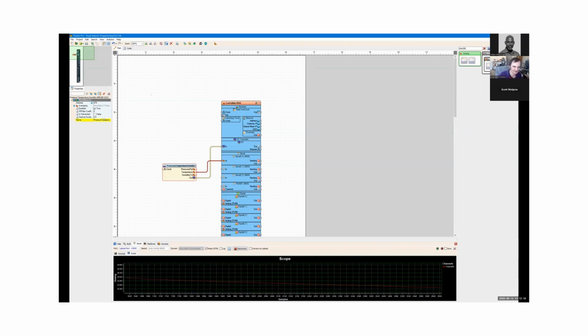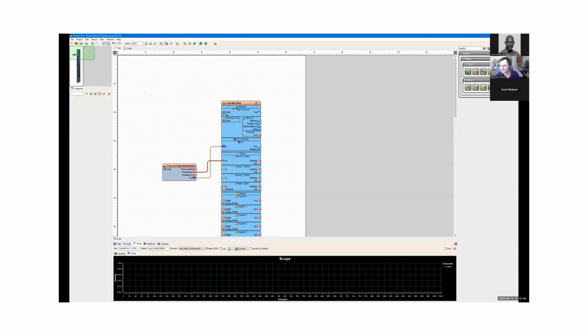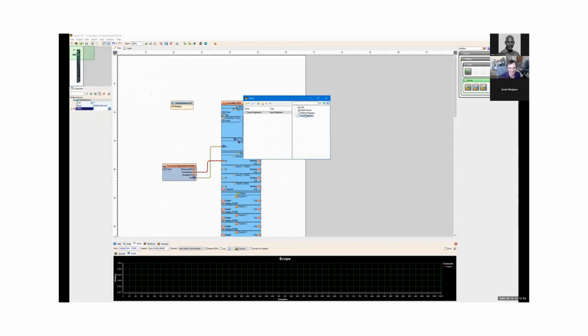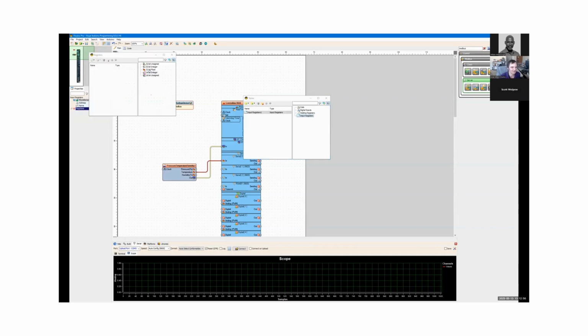So now the idea is to send that information over industrial Modbus protocol. So I'm not going to connect other sensors and stuff like that yet. Instead, we'll start adding the Modbus functionality. So I'll search for Modbus, and the first thing we need to do is add a Modbus device. And the device has tables. The Modbus works in terms of tables, and we'll just use input registers because we'll read input analog values.